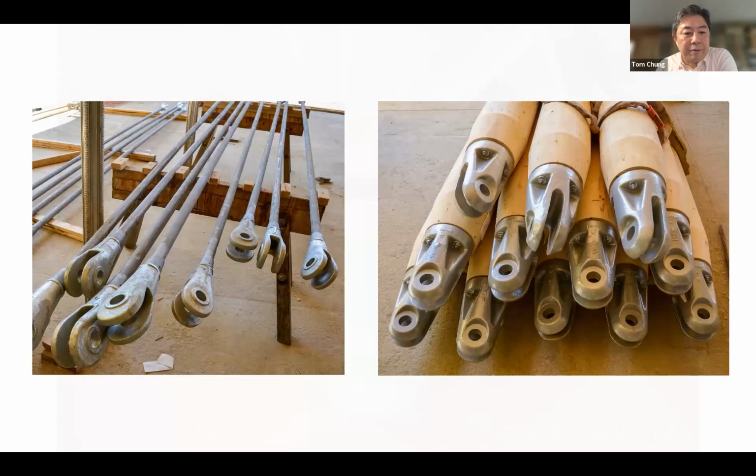Then we looked carefully at also a balance of the cost of such a connection, making sure to use off-the-shelf products, such as these tension rod ends that were commonly available to us, to reduce cost. And then where we had to cast a specific connector, making sure that we could do that with a single cast that would work for all 57 members of these joints to save on that production cost as well.